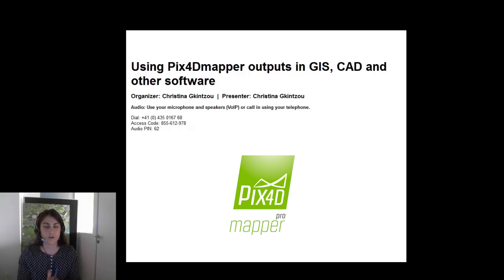So if your project is georeferenced, you will be able to open the orthomosaic georeferenced file in a software that can read this georeference and place your model, your orthomosaic, in the correct place on the Earth, and each pixel will have correct coordinates. The same happens for the DSM and the index map. Both are GeoTIFF files. They are not exactly images, they are raster files, but they don't have colors.